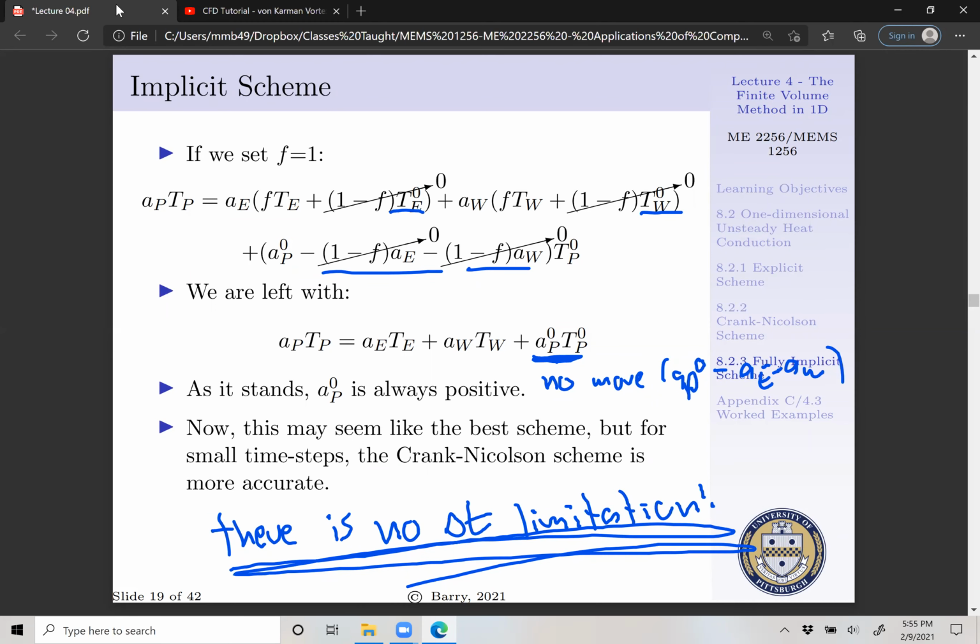Vary your weighting factor from 0 to unity in increments of, say, 0.1, and compare your solutions. So for a type of problem, you might actually find a weighting factor of 0.7 is the best that you're working with based upon the physics you're modeling, and you can run that throughout the remainder. Now, these schemes, you're going to be using each of them in homework number 2 when we talk about a transient problem. And you're going to begin to see which ones are really good, which ones are okay.